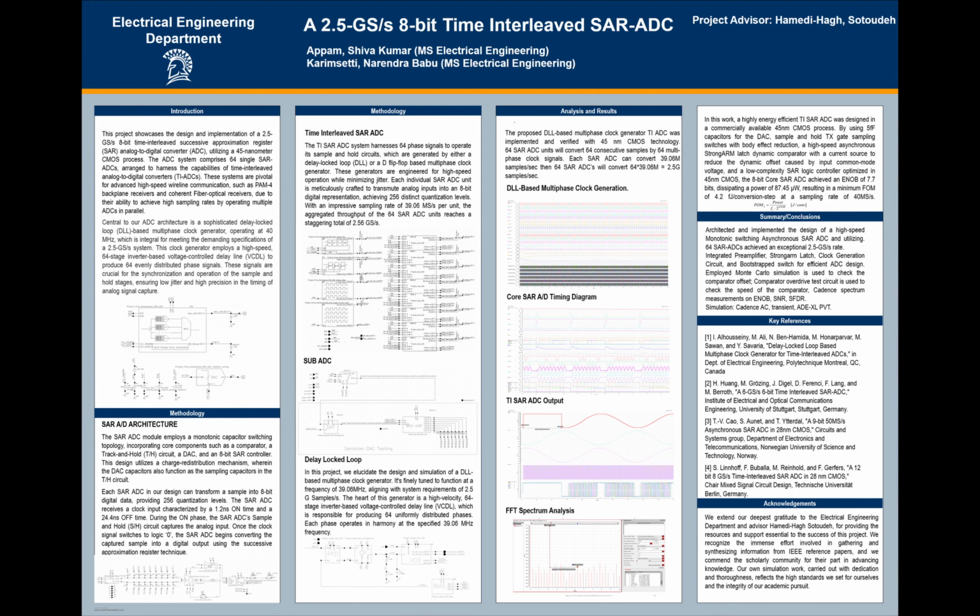For that we need a proper clock and a proper signal to get a proper output. First we implemented using the ideal clock generator, then using D flip-flops, and then using the DLLs. For the clock generation we used 3 different techniques, and ultimately we wanted to achieve the DLL based time interleaved SAR ADC.